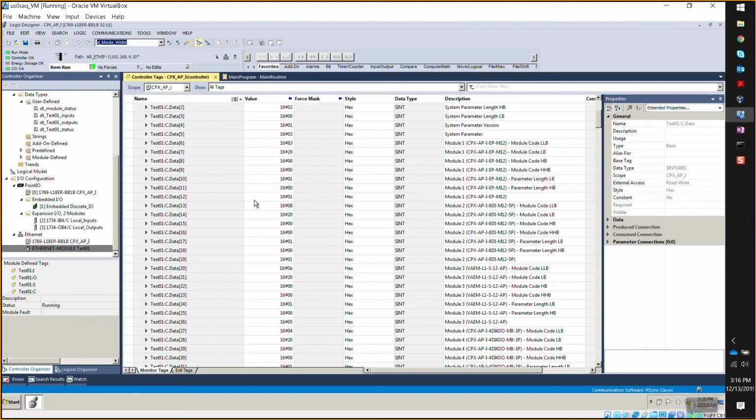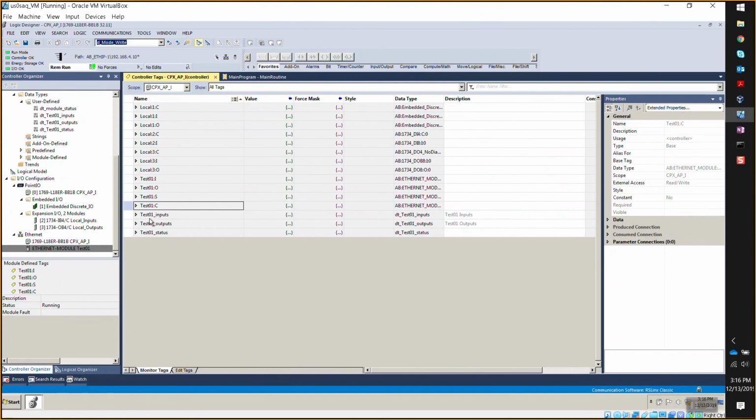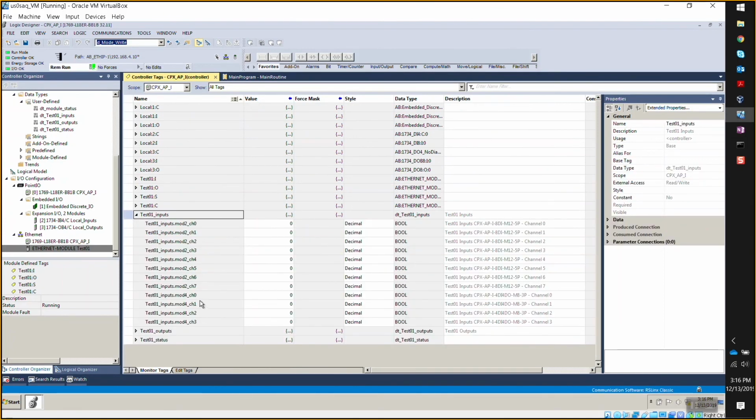No, I think the three different paths that you showed me are great. I mean, there are differences between each other, of course. I think it would be up to every programmer to follow the one that they like the most. Personally, I think in most cases I will go with the L5X just because of what I explained earlier, right? You get the UDTs, you get everything already imported in here. It takes me maybe one or two more minutes to export and import, but it's just three rungs, so it's not a big deal. Right? Absolutely. And the benefits that I get are huge compared to the other ones. I would recommend that way to go all the time.